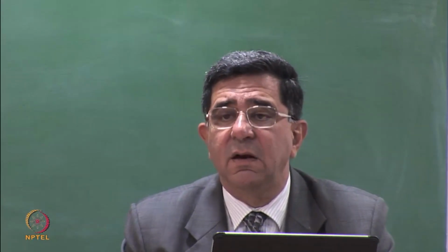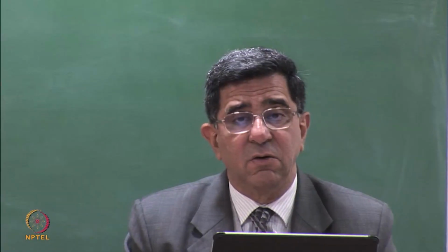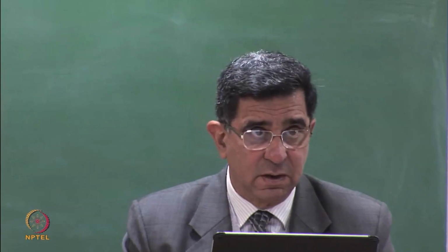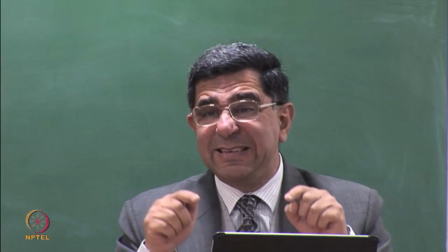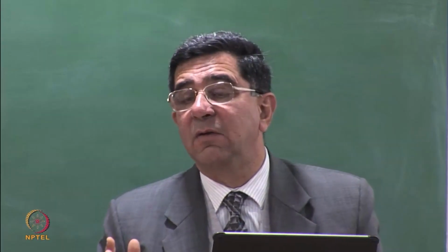Well, there is a US EPA LandGEM model. You can Google it. It's free software. The problem with all these models is they don't give you very accurate output because of the heterogeneity of the waste. And the fact that inside the municipal solid waste, it's not like a controlled environment.